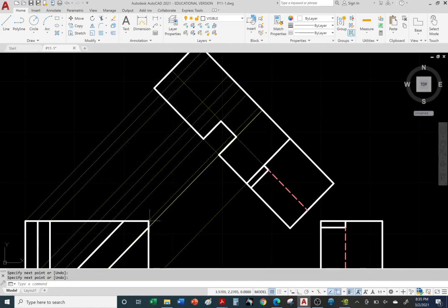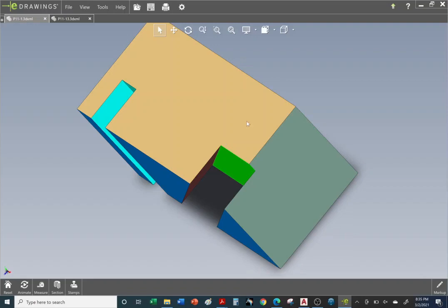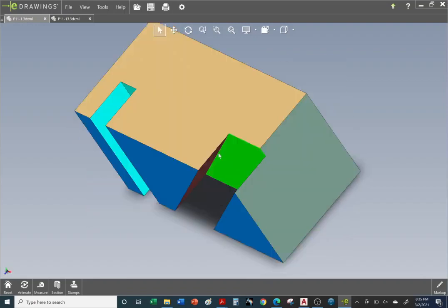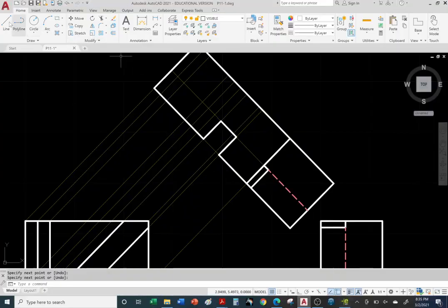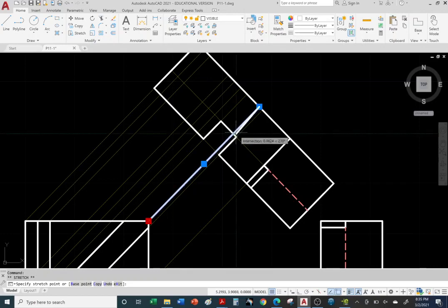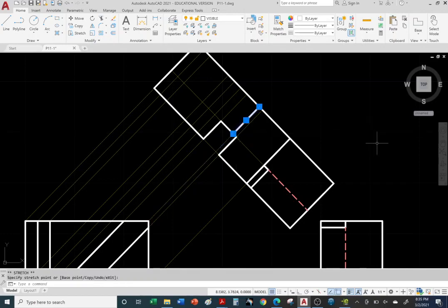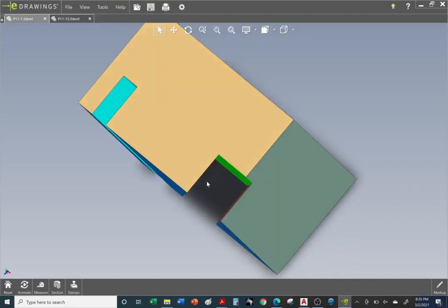All right, so now we also have that sharp corner. Okay, so if we go back, we have this sharp edge, right? You can see it now right there. So we need to draw this sharp edge here as an object line. So let's go back, line command, and from this corner here, we're going to go across, follow the construction line, and click, right click enter. And now we're going to go ahead and shorten it to the correct length. Make sure it snaps to the right place, and there it is, and hit escape. Now it looks like the auxiliary view in a 3D model, right?